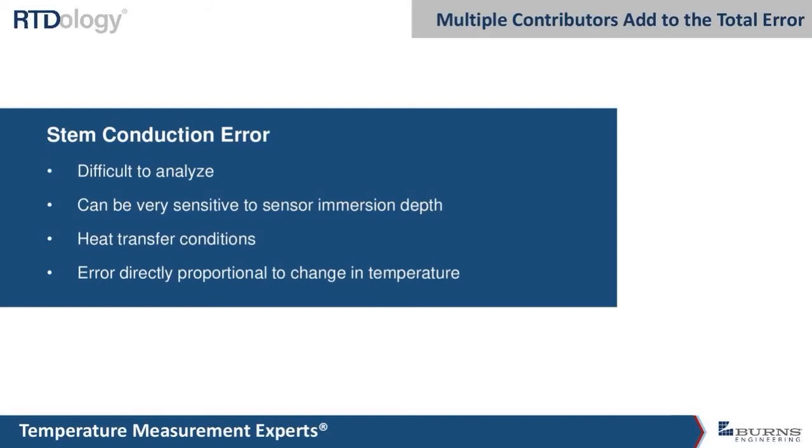A lot of the thermistors have a very high resistance value, and I don't know what the exact specs are for self-heating with those. It also depends on the conductivity of the media that the sensor is in. We did a lot of our testing in water moving at 3 feet per second, and I could imagine with a thermistor, the numbers are probably pretty similar.